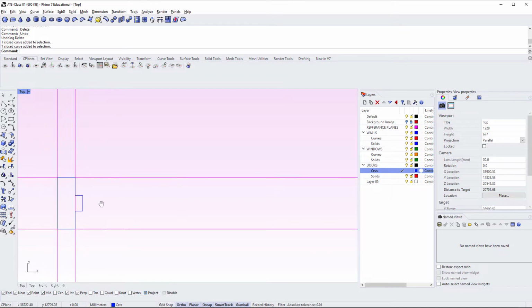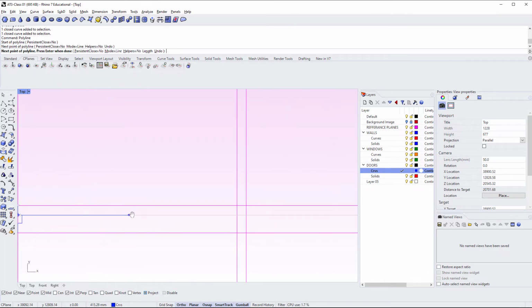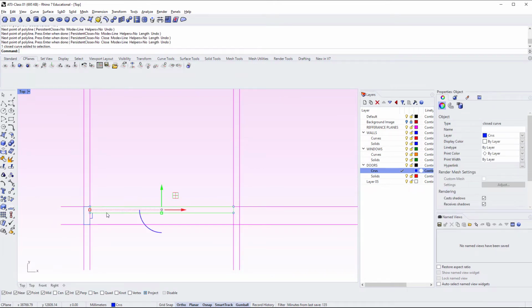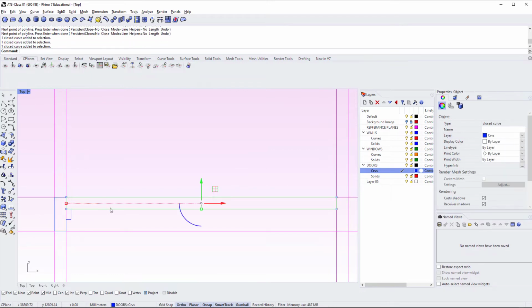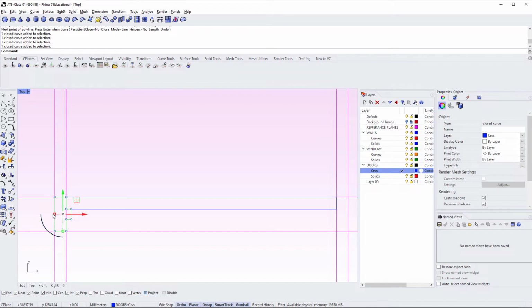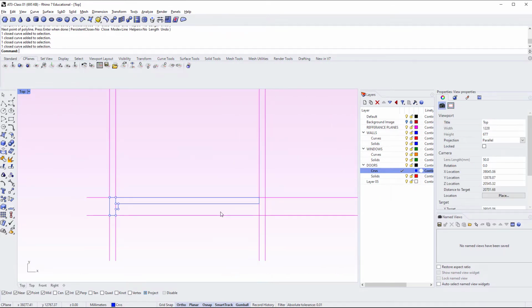That is fine. The last thing we need to do is another polyline for our actual door leaf. So I'm just going to start from this point here and move my way back, which is 35mm. That's perfect. It's basically the standard thickness of a door. Come across, go across again, back to the start. So this is actually our door ready to go. So you might be thinking, all right, so you have one door jamb on one side, but where's the other door jamb or door frame on the other side?